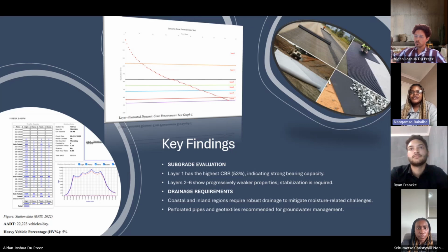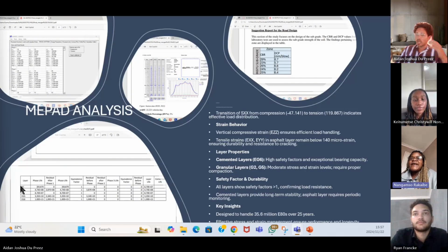The drainage system should be designed with these factors in mind, using corrosion-resistant materials for the pipes and ensuring that the drainage components can handle the corrosive effects of salt water. Special attention should be given to the geotechnical properties of the soil, as the interactions between the soil and the water, particularly in saline water, can affect the stability of the pavement. Proper drainage will help mitigate the impact of moisture-related issues such as erosion, waterlogging, and loss of the subgrade strength.